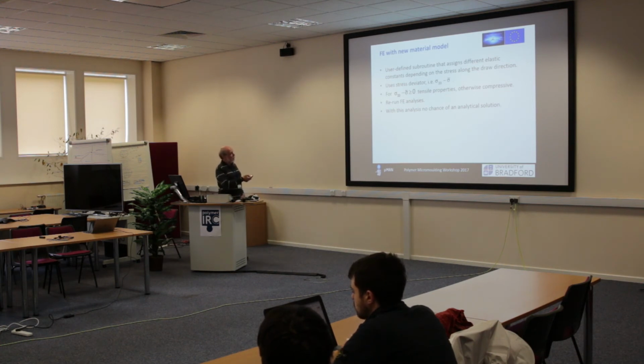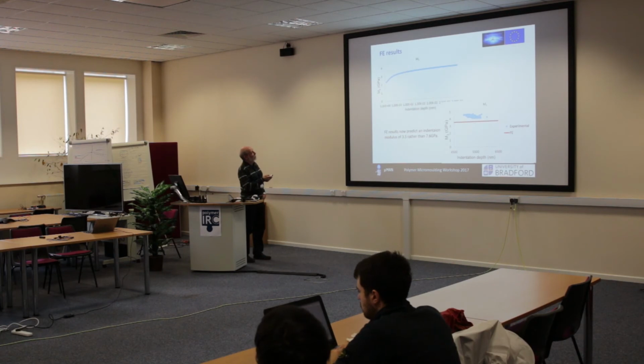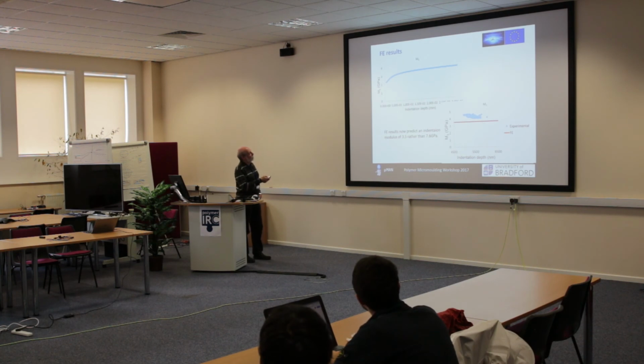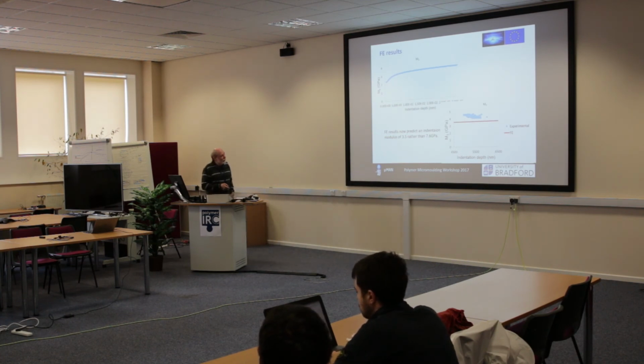Once you've assumed this, with material like this, there's absolutely no hope of an analytical solution, so we don't try. And we can produce similar FE results. For M3, just look at M3 now. See that it behaves in the same way. And this is the level we reach for the prediction of indentation modulus. Now we compare the experiments with this prediction, and we find we've got a better prediction. It's not perfect, but it's getting there, and it's reasonable.